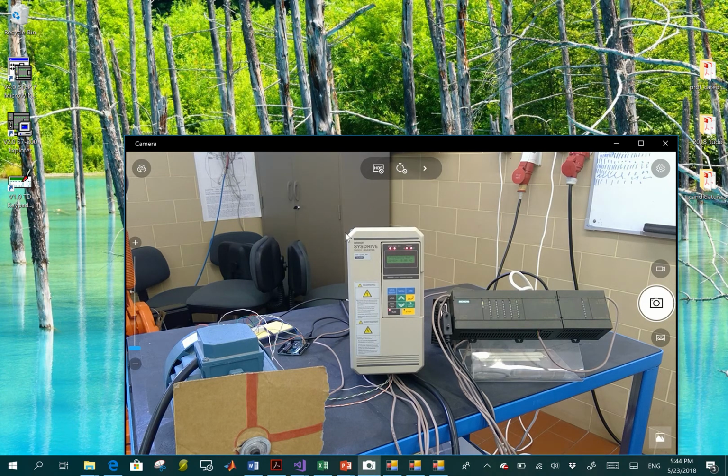This is the screen of my laptop. I have a camera pointing to the system, so I have the system in front of me. With the motor, with a card for you to notice when the motor is spinning. You see the Arduino Uno board here with the circuit to interface to the inverter. The inverter is here, the Omron SysDrive inverter. I'm using the inverter in VF mode, not vectorial mode. The PLC is here, an S7-200, a normal PLC with the analog expansion module.